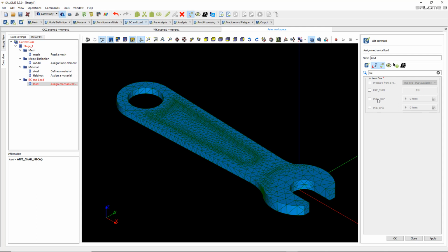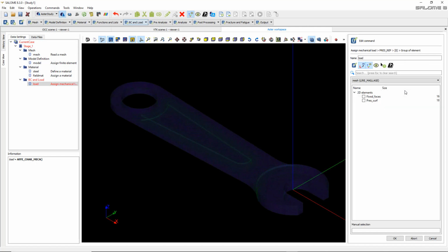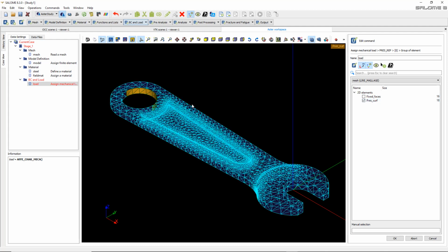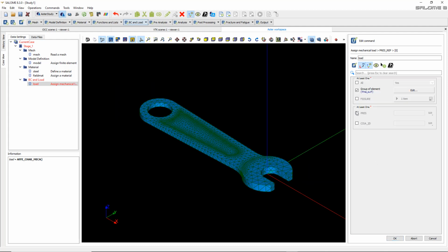Okay, anyway, the one I want to use is this, pressure rep. So why a rep? It's rep like répartition, I think, which means distribution in French. So it's like pressure distribution. And this will allow me to choose for some surfaces, this one, and give a certain value for this, and this will assign a certain pressure to this.